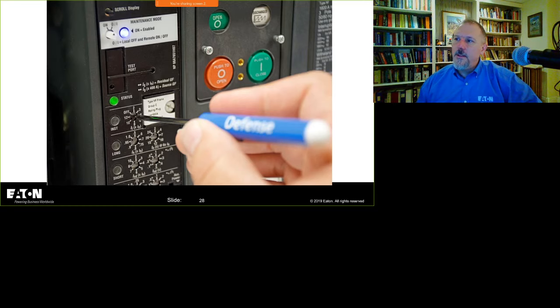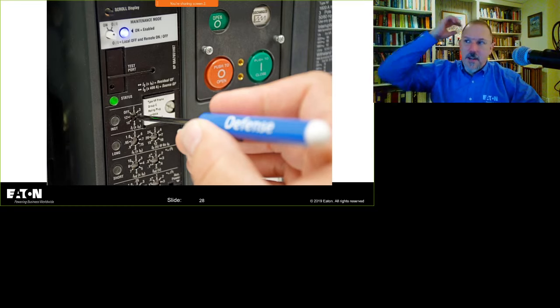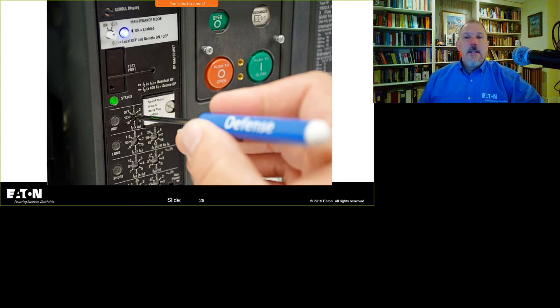And I said, "Well, David," we had a device there, and I showed him this faceplate. And I says, "Who's decided what set points to put in there?" He goes, "Oh, no, Tom. We take factory defaults on all of our circuit breakers." And I had to give him an education that when we ship these, they're all set at minimum. So what you're supposed to do is have a short circuit study and a selective coordination study. And then the coordination study, the engineer tells you what these set points need to be, and those need to be programmed.